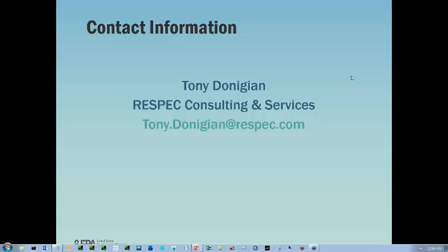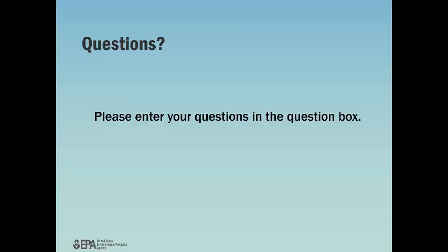Okay, great. We have a question from earlier that I thought was pretty good. If there's no specific parameter guidance available, what do you suggest starting with to help with model calibration? There's no comprehensive calibration guidance available. There are a number of documents on the BASINS website. There's Tech Note number 6, which is the parameter guidance for hydrology, to get people started on the hydrology, and that's usually the first thing you have to do. It lays out all the hydrology parameters and the hydraulics parameters and snow parameters. It has a discussion on each of them and has typical and possible ranges for each of the parameters. So you can get started on the hydrology.